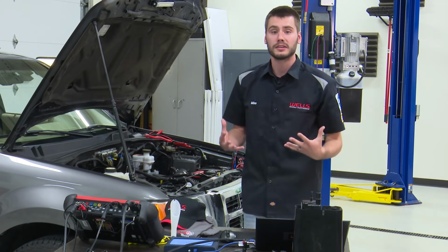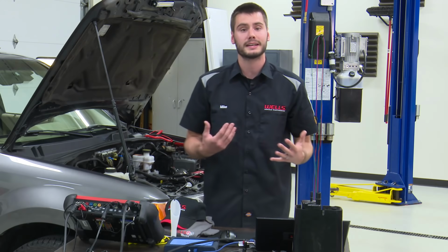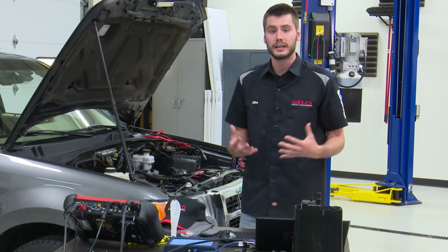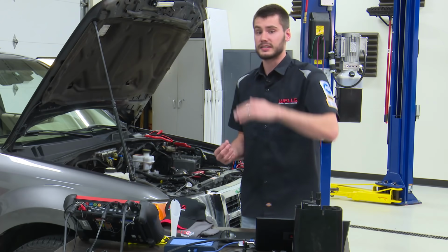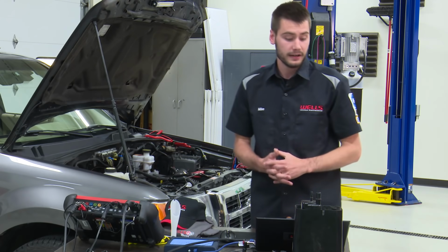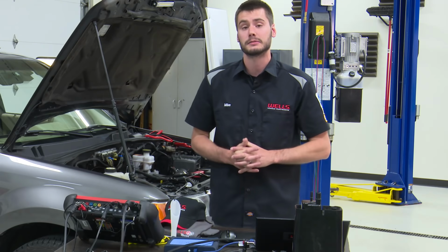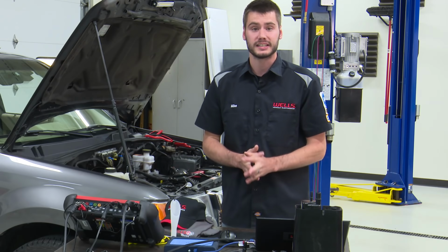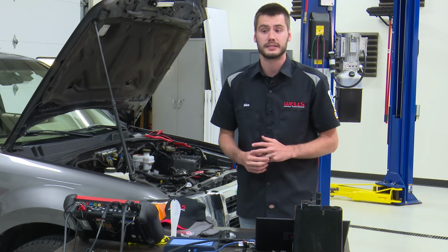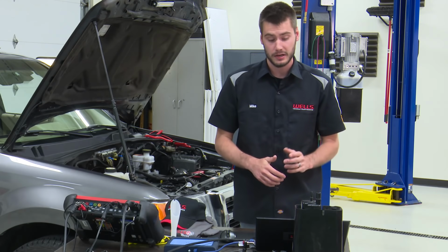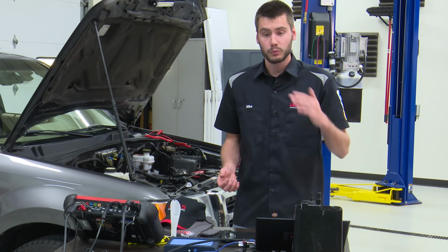And we wait a certain amount of time, depending on fuel level, depending on temperature, depending on the vehicle. We have to wait this certain amount of time to see if that vacuum decay happens. And now we'll always see vacuum decay. I have never personally tested a system that didn't have some sort of decay. Let me know if you guys have. I'd be interested to hear if there's a perfectly sealed system out there. I've never run into one. But we will see some decay.